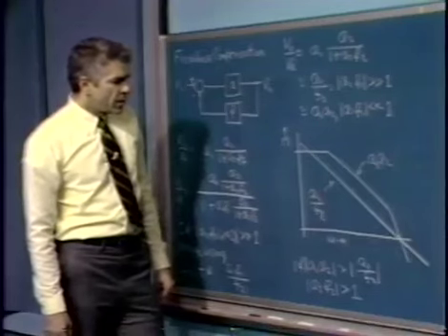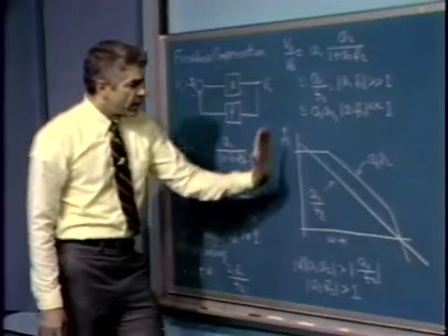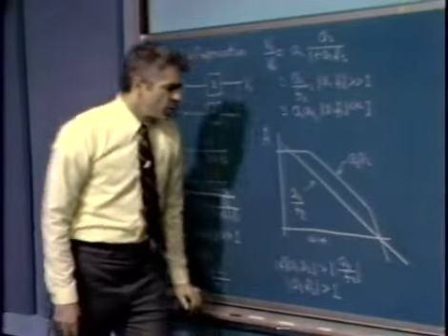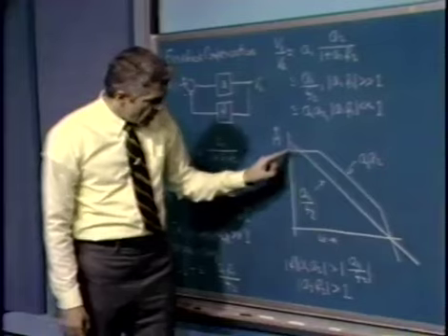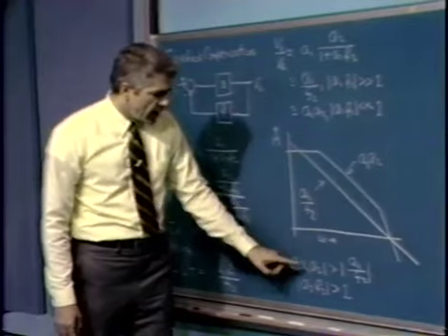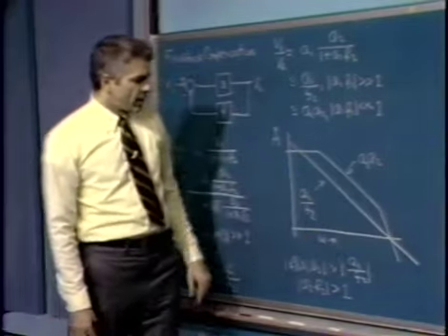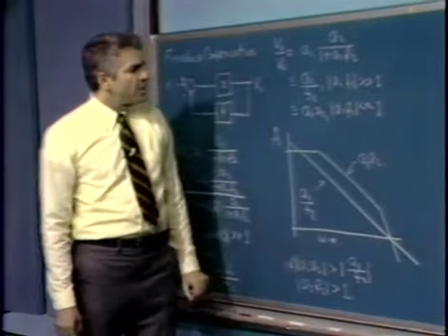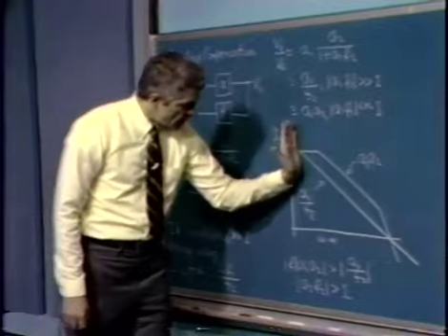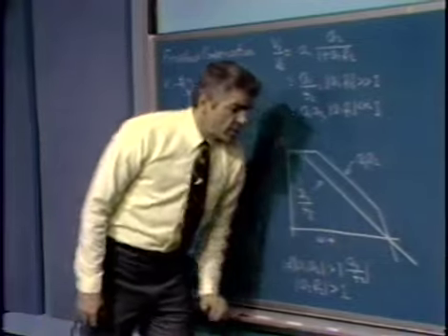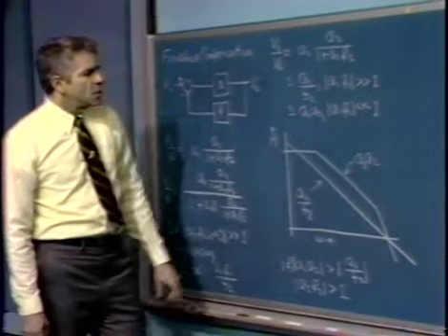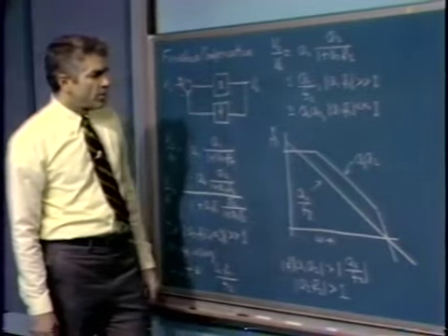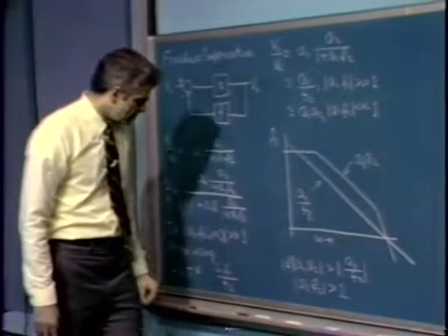If we reverse the inequality, in other words, if we're working at frequencies either below this frequency or above this one, where A1, A2 is less than A1 over F2, the inequality simply reverses, and we find that here and here, in those frequency ranges, we should use A1, A2 as our approximation to the forward path transfer function of the system.